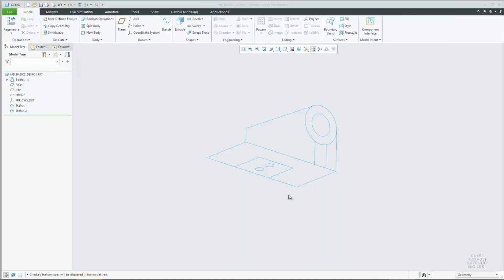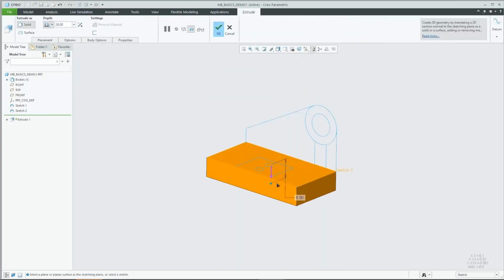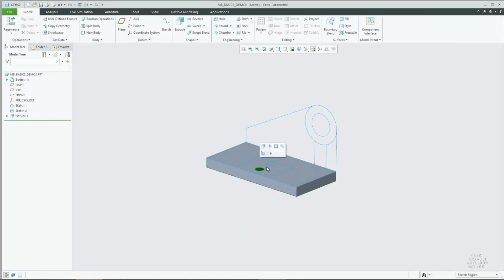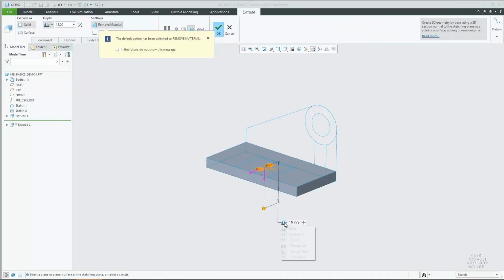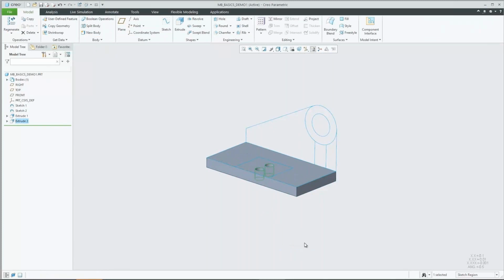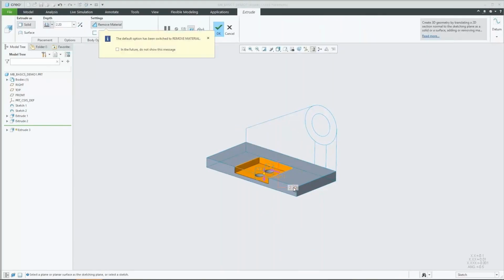So this is just a quick example. And multi-body, it's just a design method, so nothing too fancy. Make some extrudes, choose your sketch regions. So for anyone who doesn't know, this is sketch regions, which is not too new. It's been around for a couple of years, but you can select just certain pieces of a sketch to do something different with. So this isn't even multi-body.